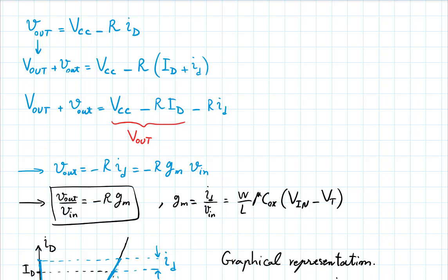Well, if I bias my circuit around a high current, it means I'm keeping it there. Even if I'm not applying a small signal to it, I have kept it at some high current. Well, I'm consuming quite a bit of power, even when I'm not feeding it a small signal to amplify. So if you want higher gain, you need to consume more static power.